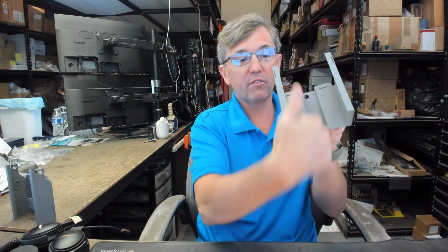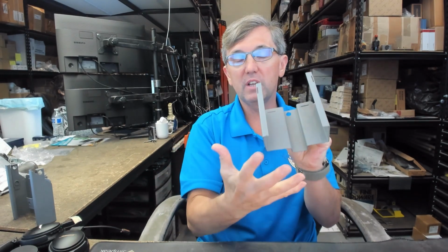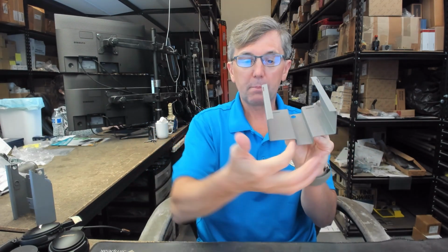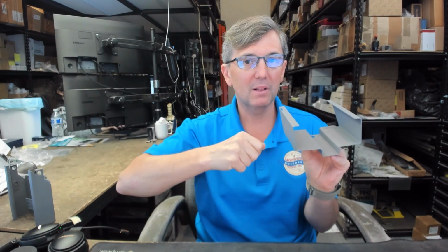And one other thing to think about as we're talking about mortar boxes or dust guards, dust boxes, is if you're doing a masonry frame and it's going to be filled with concrete, and you're going to need to come back later and drill the frame wherever for surface applied hardware, you'll generally take the header and weld reinforcement into it, wherever you need to have reinforcement, because you're going to drill and tap. You're going to drill and then tap. That piece of steel will be welded in there. And one thing that people will do is the installer, usually not the mason, because the mason's not the guy drilling and tapping later on, or just drilling.